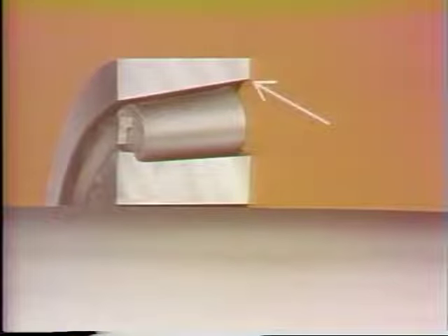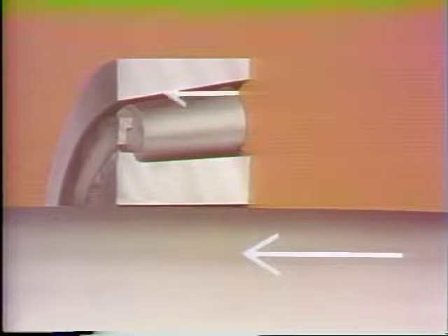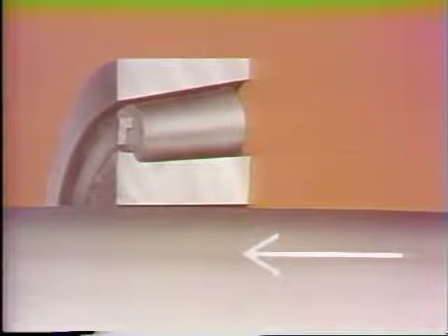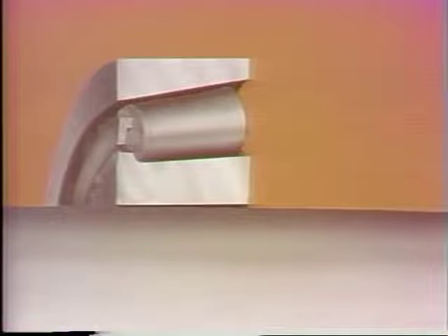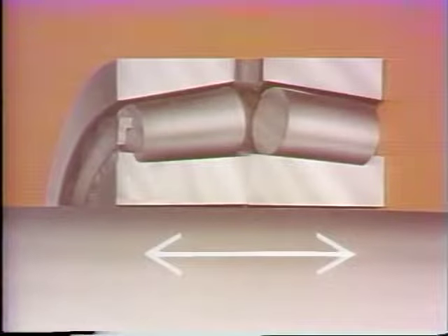This ring is stationary, and this one moves with the shaft. The tapered rollers keep an equal distance between the two rings and prevent radial movement, just like the rolling contact bearing we saw earlier. The tapered rollers also prevent axial movement. If the shaft tries to move this way, the rollers meet the outer ring and the shaft is unable to move. Now remember, lubricant in the bearing prevents actual contact of the parts. This bearing will prevent axial movement in this direction only. But the addition of a second bearing will prevent axial movement in both directions.